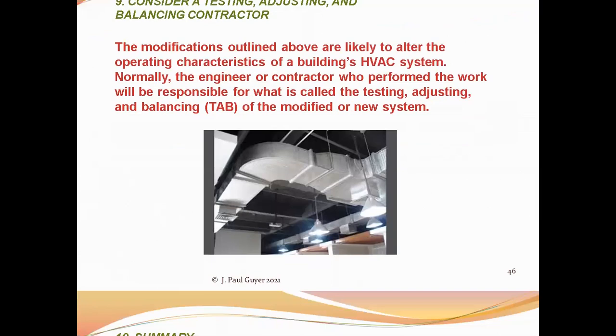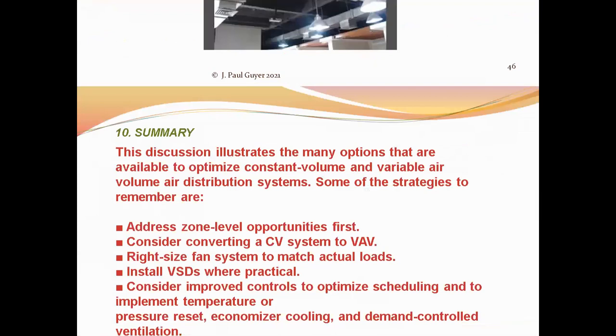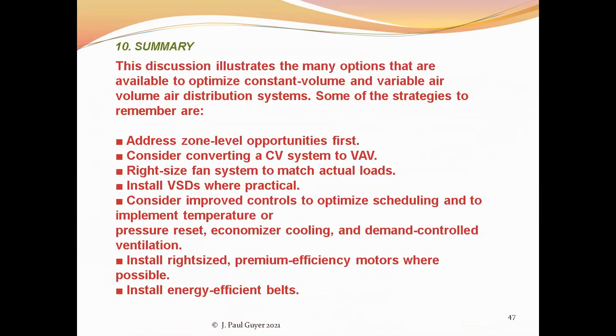So the strategies for improving the energy efficiency of older HVAC systems. The approach: first, address zone level opportunities, thermostats, resetting them, replacing them perhaps.